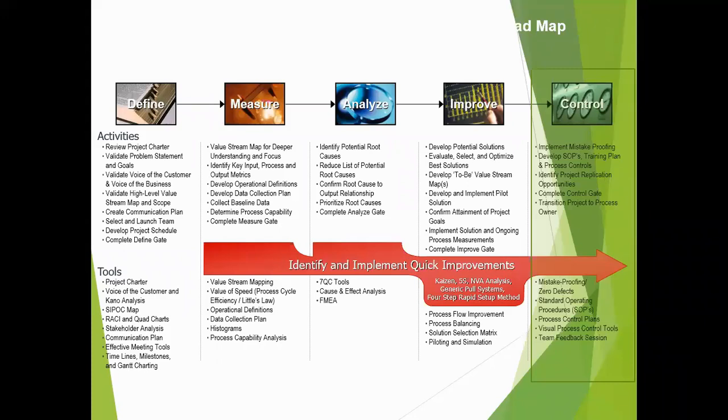Okay. So let me see. Variation. We got process variation. Yeah, it's process or product variation. Second, measurement system variation or gauge variation. Yeah, I got that. The measurement system, the MSA. And these two put together is called the observed variation or the actual variation. So you minimize measurement system variation by doing a gauge study.